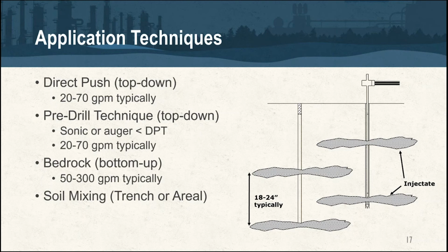The pre-drill technique, which I'll discuss separately in a minute, is essentially using sonic or augers to get down past whatever that refusal is, right? So if it's fill material, if it's cobbles, if it's weathered bedrock, backfill that with hydrated bentonite and then re-drill with direct push. So the flow rates are going to be similar between those two methods. Bedrock is advanced bottom up. The packers, just in case any material sloughs in, you want to do that in a bottom up fashion. The flow rates there can vary a little bit more.